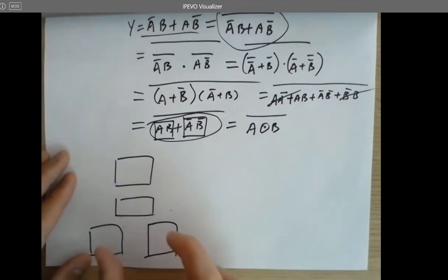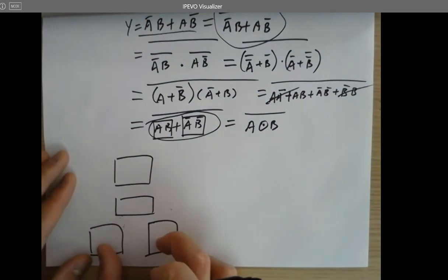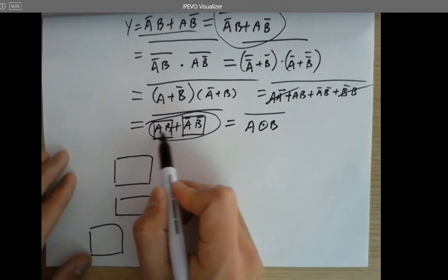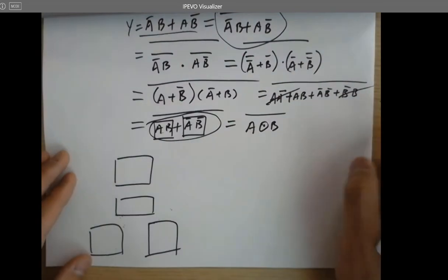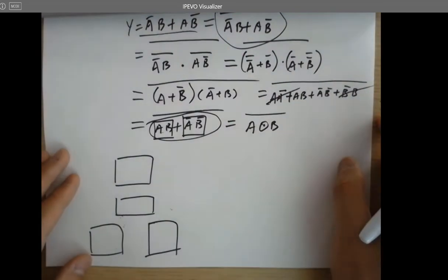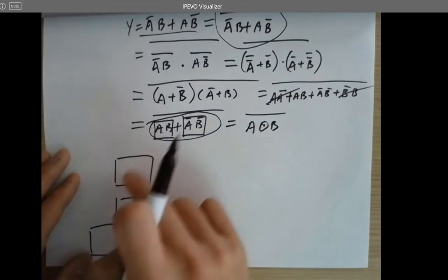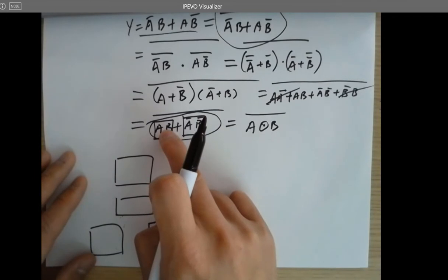So that will be something that looks like this, right? In series, in parallel for these two boxes. So now I want to implement the logic inside each box over here. So now it's AND logic. So in each box, AND logic should be in parallel for PMOSes.